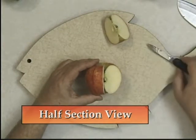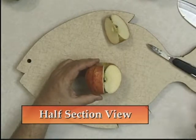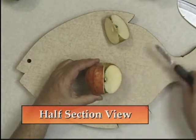I usually use half section views for objects that are symmetrical about an axis. And by using a half section view, if someone wants to know what's inside the object, they look at the half sectioned half. And if they want to know what's on the outside of the object, they look at the unsectioned half of the half section view. Let's take a look at a revolved section.